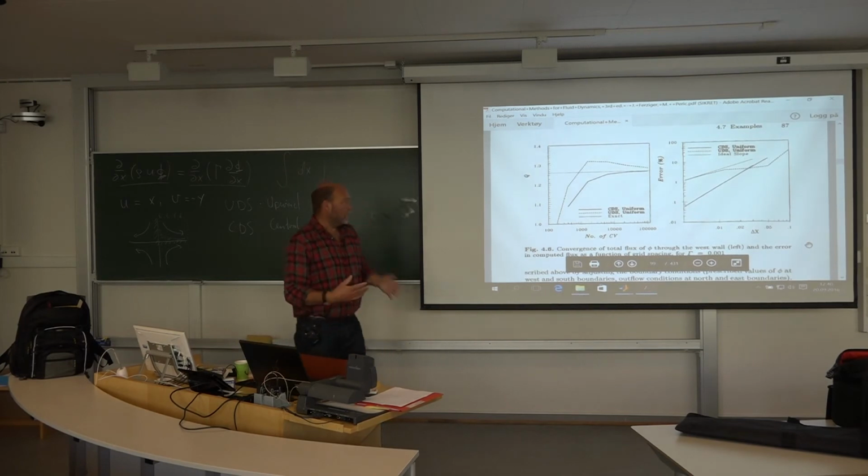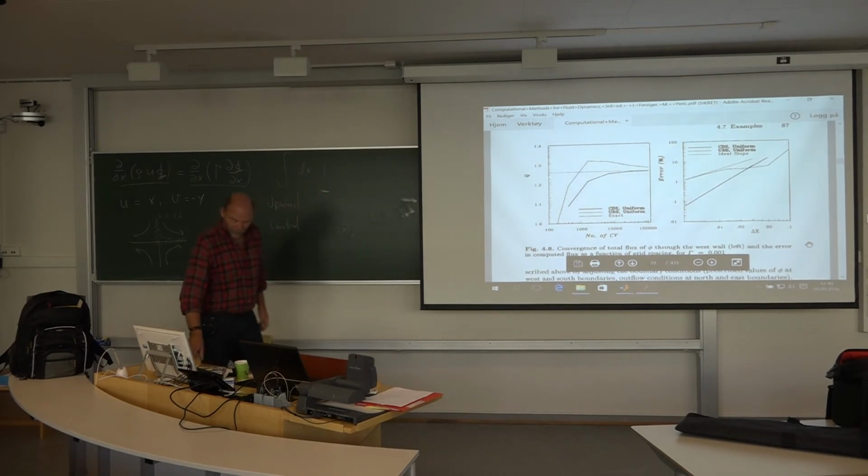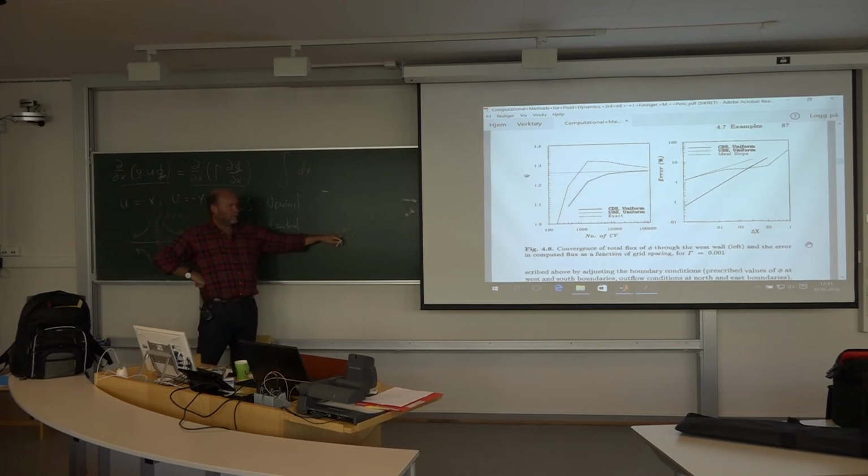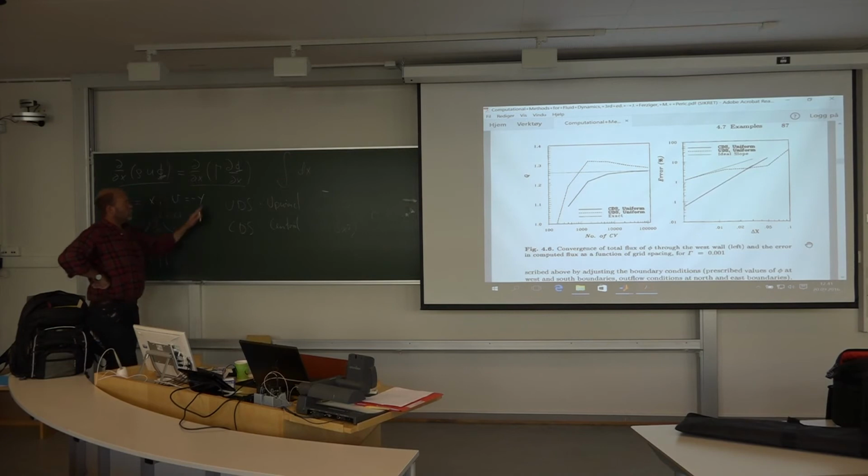So you have something you have to decide for yourself. Okay, the upwind scheme is inaccurate but stable. You can get a solution faster. Central scheme, higher accuracy, much better. Not so much false diffusion as we called it, but it can be very jumpy, can be very unstable, can be hard to find a solution. So you have to choose here.